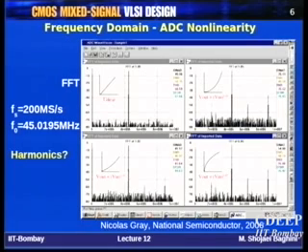So when you want to look at harmonics in a sampled signal, suppose you have an analog signal and because of nonlinearities you get some harmonics. That means your signal bandwidth is not limited anymore. Now if you sample this signal, there will be a little bit of aliasing, because you have harmonics.